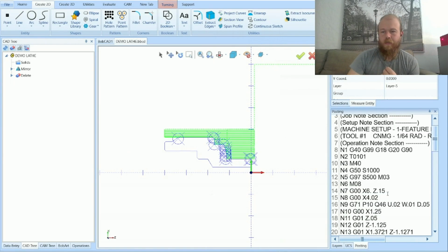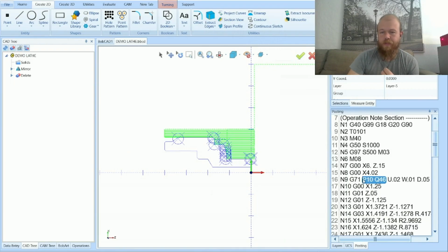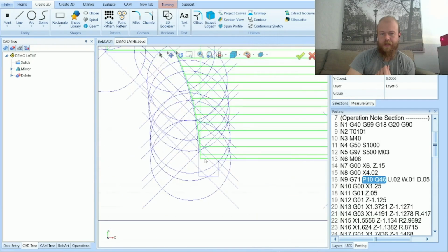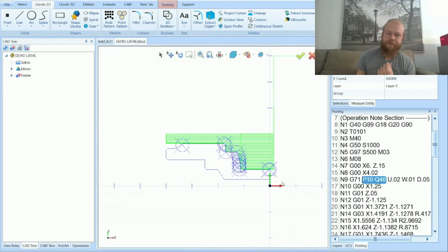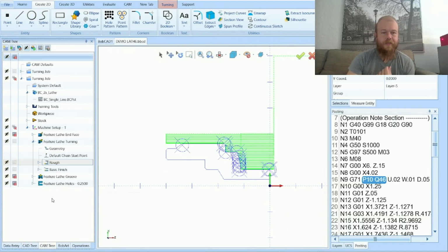And also, when you get the hang of using can cycles, you can see I'm getting there, you can just plot the points like this and then be able to see, okay, the profile looks correct. Let's run it from there. You don't have to look at plotting a couple hundred lines of code. You can just plot these, it's about 20 points here, and make sure every point lines up with a corner there, and then you've got your profile. And your G code, you can double check your work pretty easily.